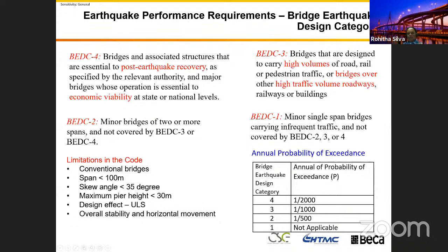What is the post-earthquake recovery? A good example is the flood. After a flood happened, you can see there's a cover in the piers. Like when an earthquake happened, we haven't seen that one. So when the earthquake happened, the bridge might be cracked. The expansion joint might be jammed. The bridge deck might be dislodged. So you can't let the traffic, or you can't let the people, drive.